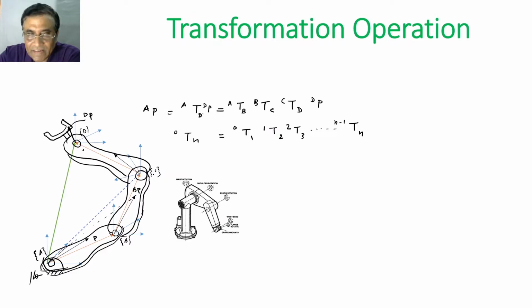The reason is, you see, the homogeneous coordinate transformation matrix does not carry the physical information of a generalized link. Say this intermediate link is twisted. That means one end with respect to the other end, and it may happen, right? In a generalized way, I can construct a robot where any link between two axes of rotation could have a twist.